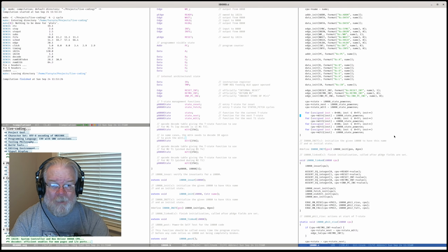So B2 is going to provide support for fetching the second byte of multi-byte instructions. By multi-byte instructions, I'm not defining a multi-byte opcode. I'm saying that if you have a 1-byte opcode, which is all you have in the 8080, followed by an immediate, like this MVI is going to use, that's a multi-byte instruction for the purposes of this simulator.